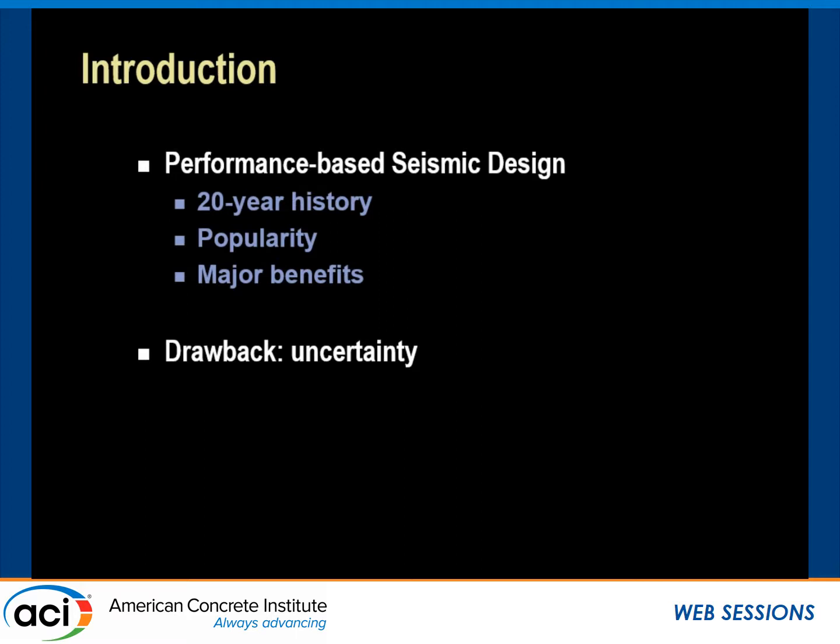Typically the SLE and the DE checks are pretty easy. We do them quick and early. We don't actually perform the MCE check until later in the design process because it does take a lot more work. We like to have the design as set as possible before we do that. And for that reason, there can be some unpredictable results that come out of the MCE phase. So we set out to try and reduce those unpredictable results.